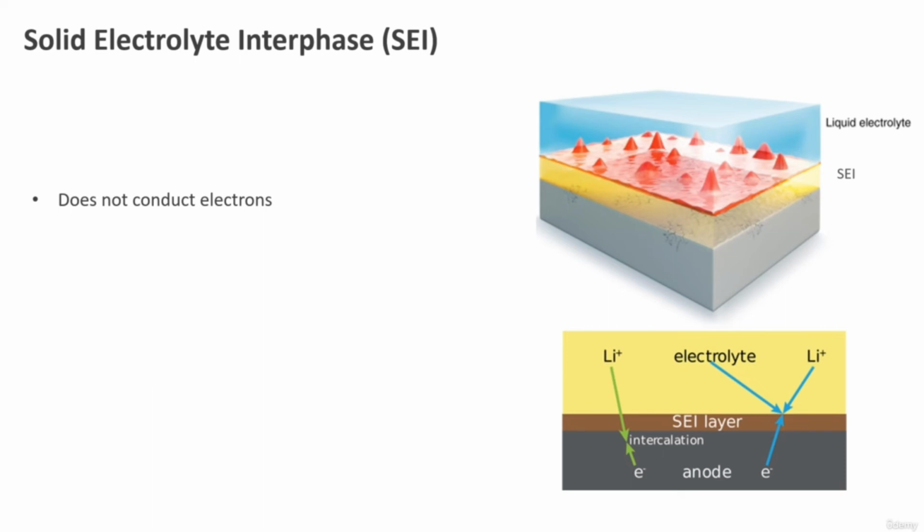In that case, electrolyte decomposition is passivated, similar to the thin aluminum oxide layer that prevents aluminum from oxidizing further when exposed to air. The SEI should conduct lithium ions, allowing the necessary lithium-ion transport during battery charge and discharge. Electrolytes are optimized to form a stable, electronically insulating and lithium-ion conducting SEI, aiming at a long battery cycle life.